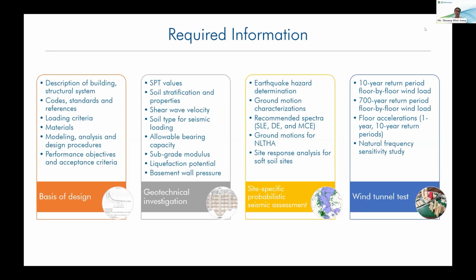And the second one is the geotechnical investigation. The geotechnical consultant will provide us the soil bearing capacity and subgrade modulus to use the soil springs in our models. They also check the soil type for the seismic loading. If we have a basement wall, the consultant will provide the basement wall pressure under earthquake. If the site is on soft soil and there is liquefaction potential, they will check the liquefaction effect in the soil and also provide the lateral subgrade modulus for the piles, which is reduced due to the liquefaction effect.